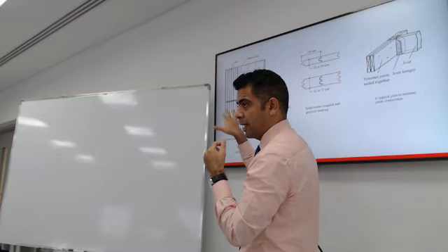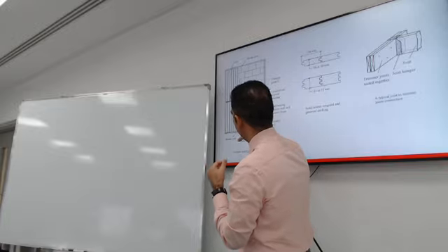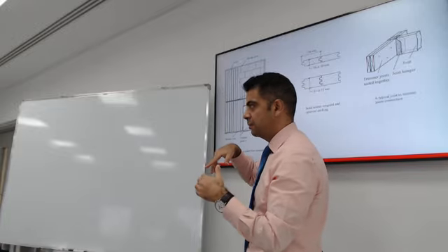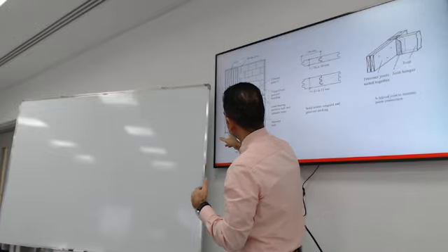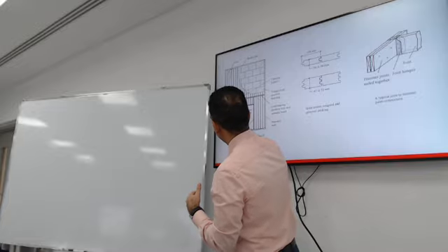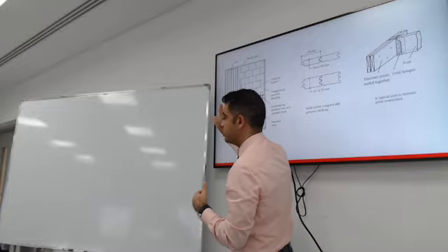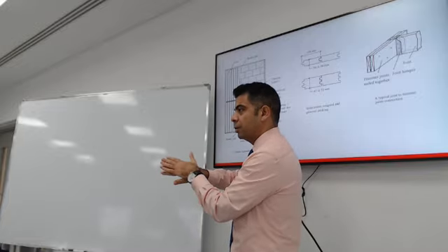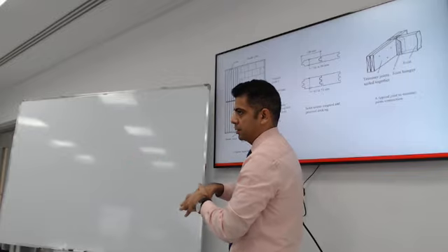This is a plan view. This is an opening for a staircase. So these are the joists, and do you see how they are running every so often? So when you put the plywood on it, the plywood is not spanning too much.